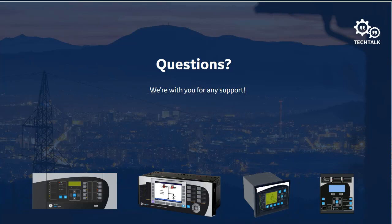What is the maximum value that you would expect negative sequence or zero sequence current or voltage to be? It's a great question. What's the maximum value that we would expect negative sequence or zero sequence quantities to be? When we talk about current, we never expect to see the negative or the zero sequence quantities larger than the positive sequence quantities.